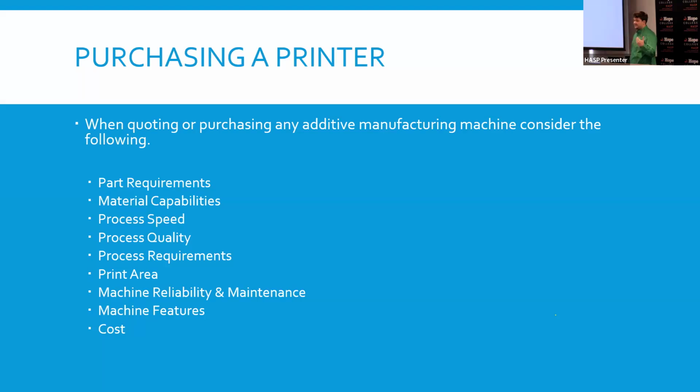I'm going to go buy something akin to material jetting that has a nice smooth surface. Process requirements. I mean, if I'm going to use titanium, I'm going to buy an SLM printer instead of a DMLS. I need the hotter heat.